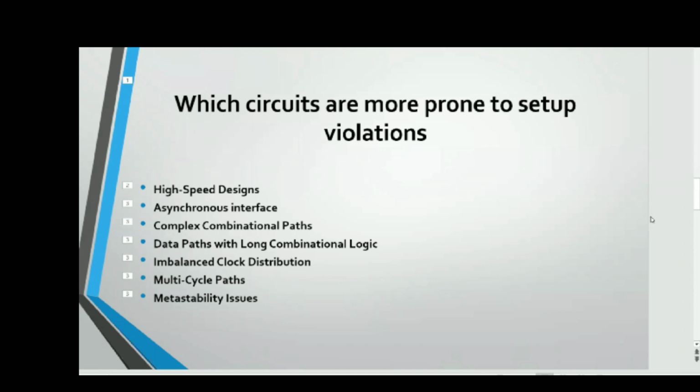So in this video, we are concentrating only on the setup time. Right. So I hope that this concept is clear, that this is the minimum amount of time where the data must remain stable before the clock is arriving. Otherwise, it may lead to the data not being properly captured by the capturing flop.